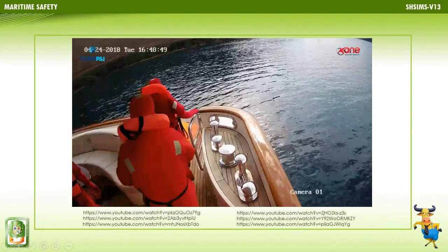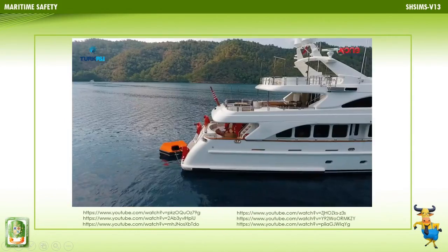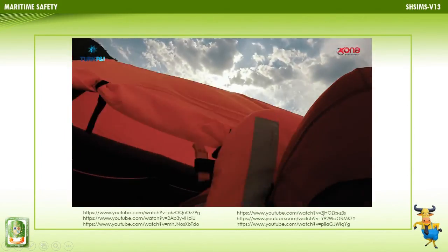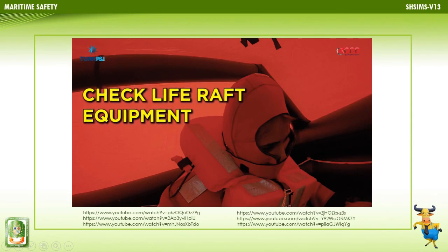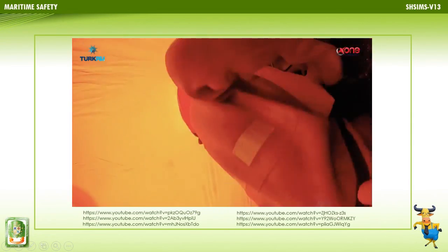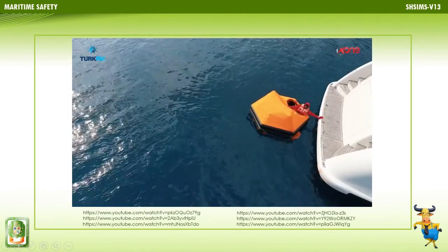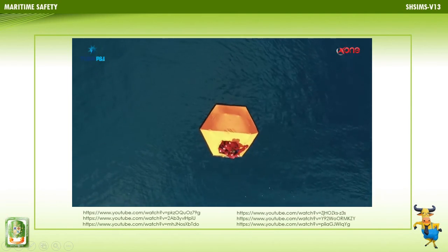To evaluate the safety precautions and topics for the overall operation of disembarking the yacht and embarking the life raft. Each survival craft should be stowed in a state of continuous readiness so that 2 crew members can carry out preparations for embarking and launching in less than 5 minutes. Remember, a drill can be paused so that any difficult elements can be explained.